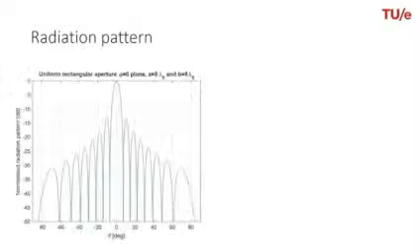Now, this is shown in the next example. So this is a two-dimensional radiation pattern of a particular antenna with a certain aperture size. So you observe along the horizontal axis theta in degrees, ranging from minus 90 degrees to plus 90 degrees. And we have expressed the normalized radiation pattern in decibels, in dB, ranging from 0 in this case to minus 50 dB.